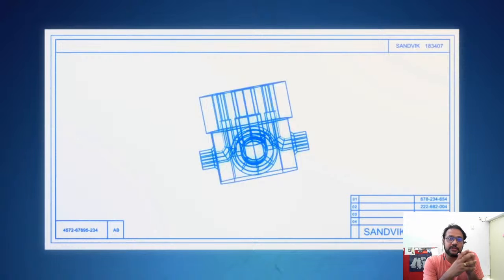The choice of the near net shape depends on a lot of things. One of the key things, besides the cost and production constraints, is the stresses. Whenever you are designing, let's say you are making a forged part, the near net shape should ensure that whatever features come under a lot of stresses are properly thought about, and are not removed without consideration from the near net shape. Okay.